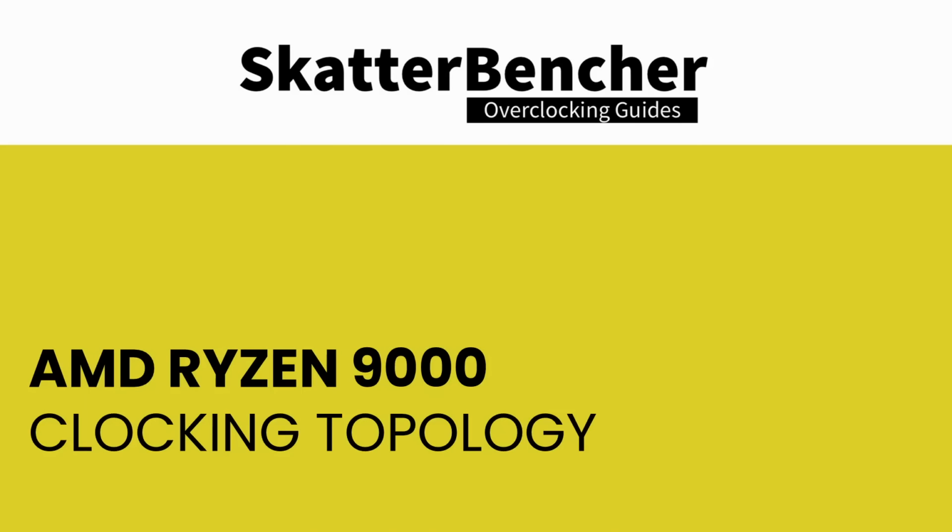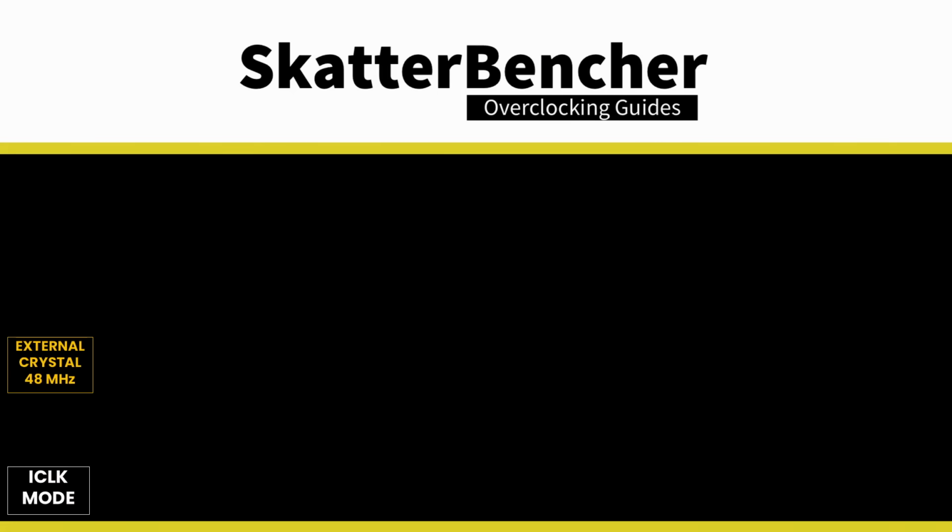To better understand the performance tuning opportunities of the Ryzen 9 9950X3D, let's have a look at its clocking and voltage topology. The standard Granite Ridge platform has a 48 MHz crystal input to the integrated CGPLL clock generator.